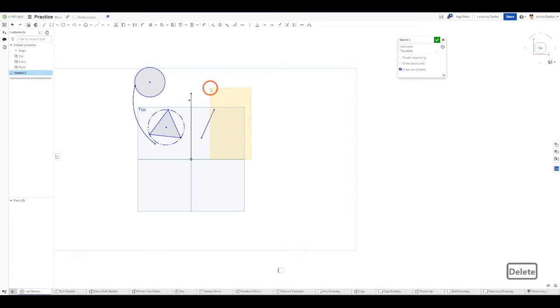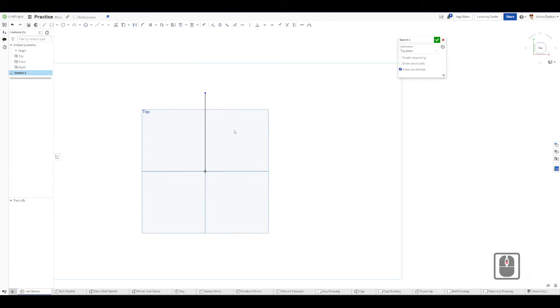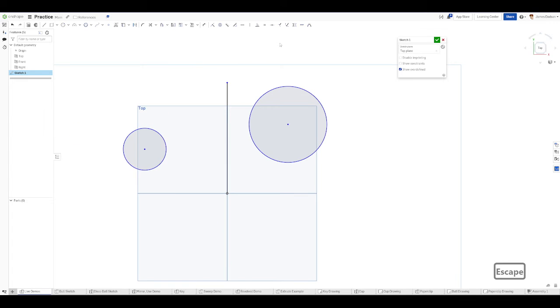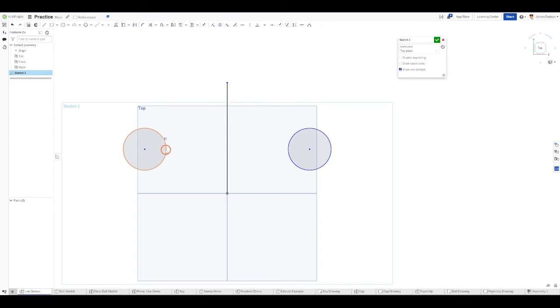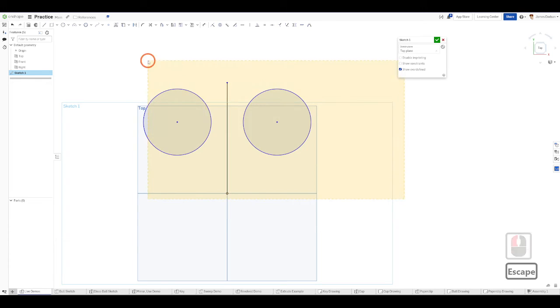And there's even a way to add symmetry after the fact. So if I have two shapes that I've already made and I want them to be symmetrical, like I have a circle here and a circle here, they're clearly not symmetrical. This tool over here on the top right, that sort of looks like two M's mirrored across a line, I can click on that one and then click on the first entity, then the second entity, then the center line, and it will make them symmetric. So now everything I do to one happens to the other as well. So this is a super useful tool.